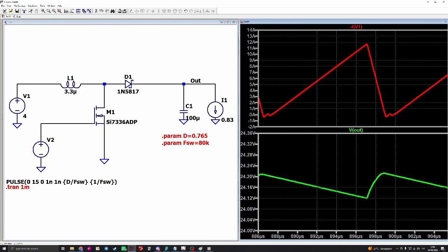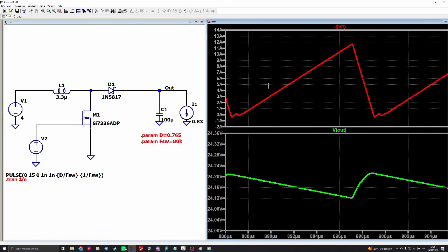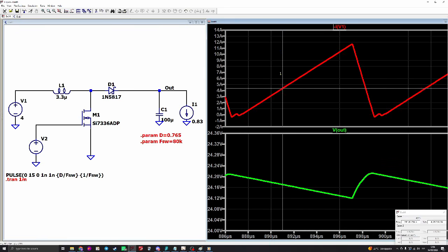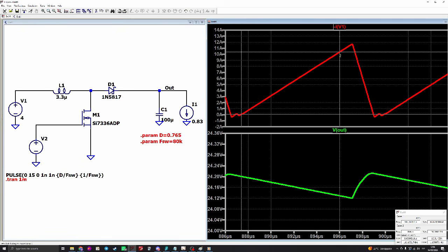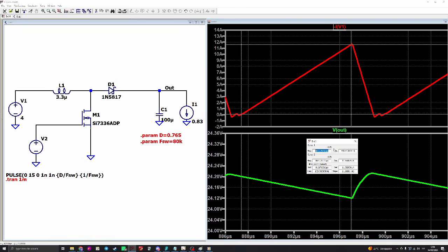And as you can see also, here we have a very small T off. Let's verify that the T on is similar. So it should be basically 10 microseconds. Let's see if it is true. Okay, how much here we have? Guys, we have 9.61 microseconds. I mean, the calculations are proving almost real.